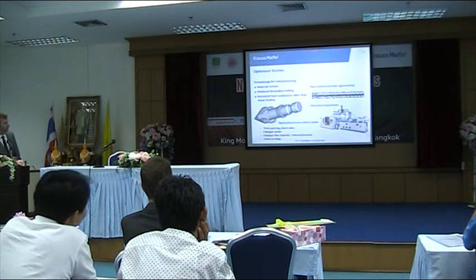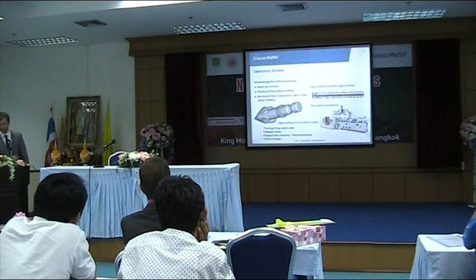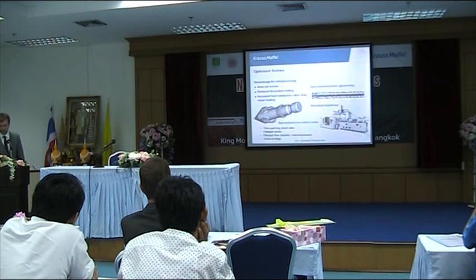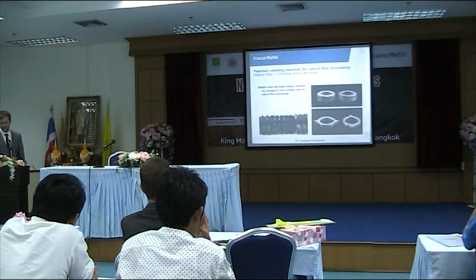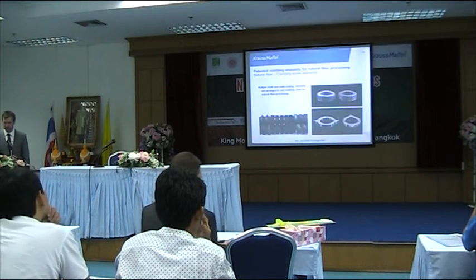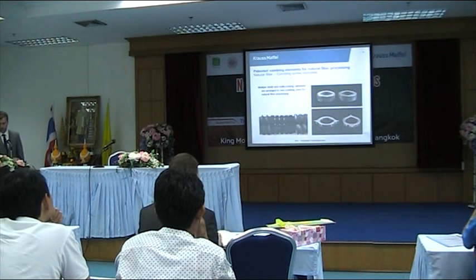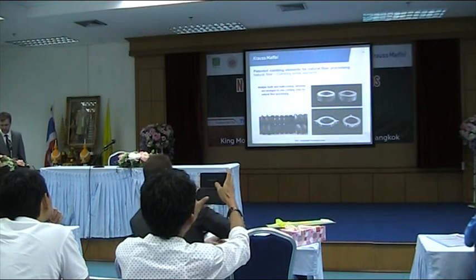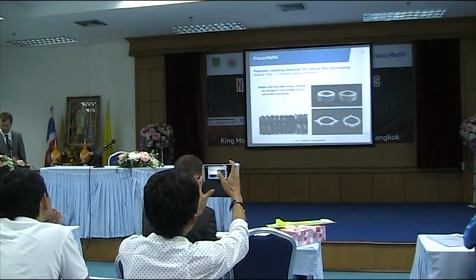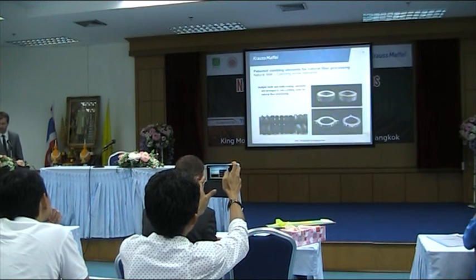And you can also use a specialized non-return valve with an enlarged stroke or enlarged flow channels, so you do not destroy fibers inside. Also for the injection molding compounder, we have multiple tools and multi-combing elements that are arranged into one combing zone for natural fiber processing.